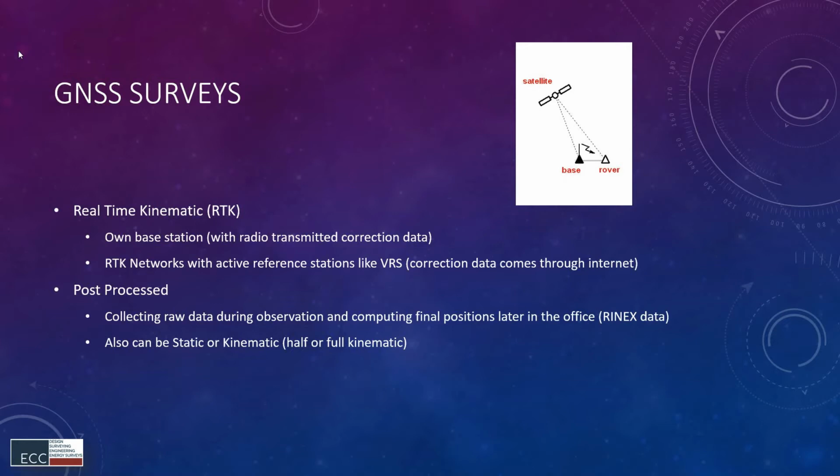So this post-processing will be done in 2 steps. The first step is from the RTK network points, with a vector we calculate the baseline to the base point.